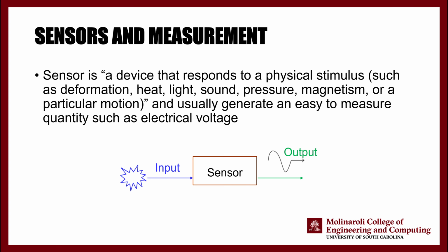Modulus of elasticity is a material property, and we are very interested in this property because it will help us design whatever we need to design, right? So how can we calculate this modulus of elasticity? Meaning, how can we do any stress and strain measurements? All of these measurements are done through sensors. In your bending and torsion lab, you have already used two digital sensors.